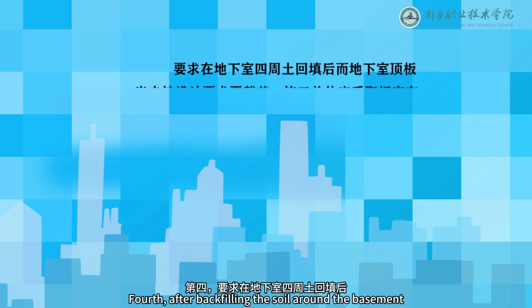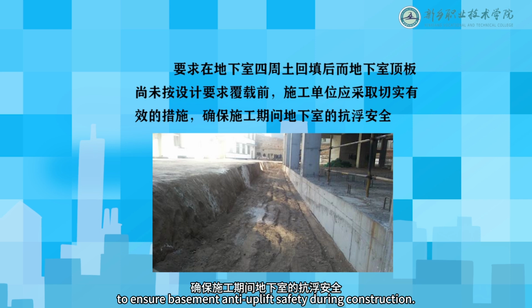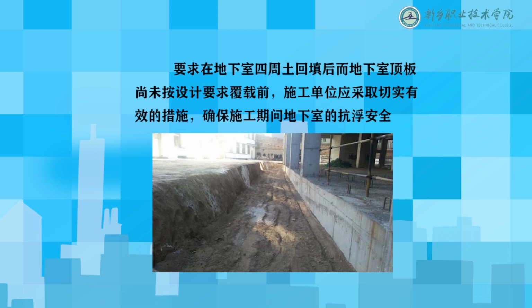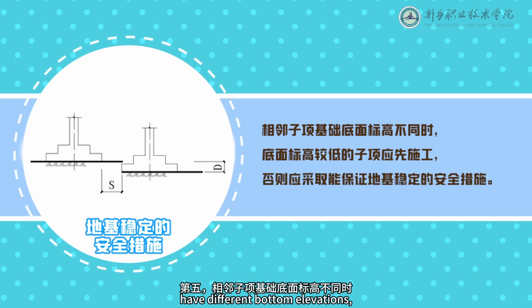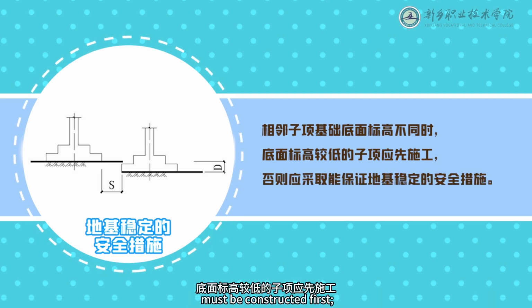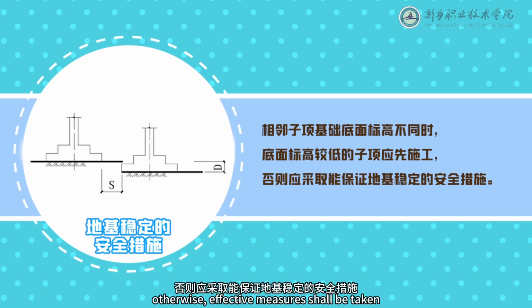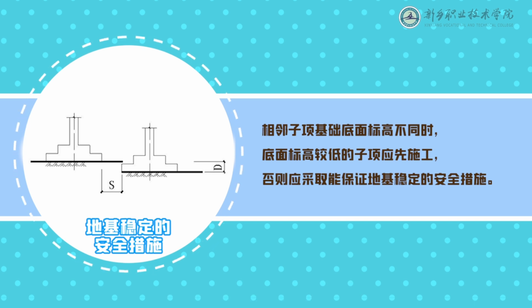Fourth, after backfilling the soil around the basement, but before the basement roof is loaded as designed, contractors must implement effective measures to ensure basement anti-uplift safety during construction. Fifth, when adjacent sub-item foundations have different bottom elevations, the one with the lower elevation must be constructed first. Otherwise, effective measures shall be taken to ensure foundation stability.